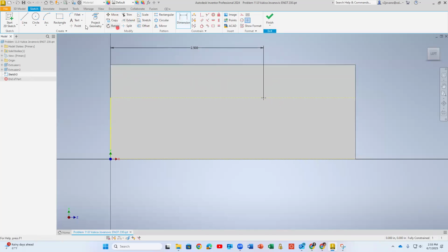And another one, so I will make another point just outside, and then I would like to use coincident to say that I would like this point to be here. And you see, it didn't become yellow. This became yellow. So I can switch this to, if I select that, switch to invisible geometry, and then I can dimension my other point.